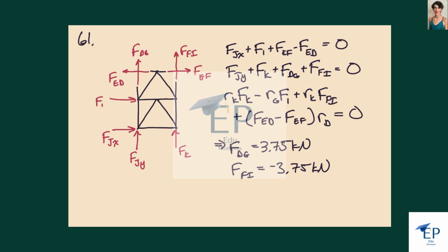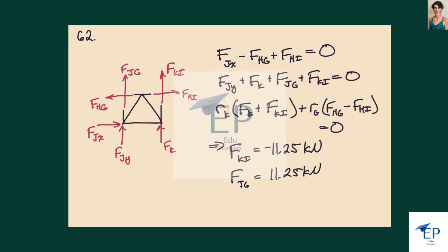but we'll be able to figure out what the difference is. So we make the cut and we expose our forces in this horizontal member and the two forces in the vertical member. So we actually again have four unknowns, but we're only going to have three equations. Summing the forces in the x direction, in the y direction, and then the moments about this point here to give us our three equations.